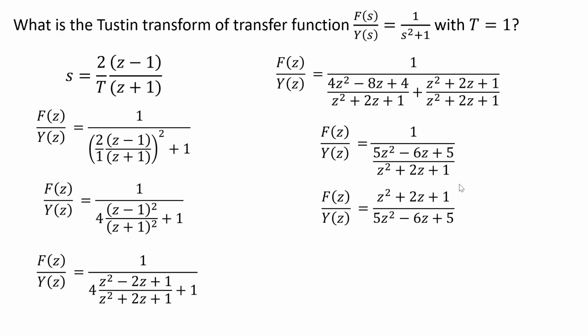because that basically means the past. Anytime you have z with a negative, that's the past sample. Z negative 1 is the last sample, z negative 2 is 2 samples ago, right? And so it basically just takes some algebra to figure that out. But once you have it in that form, then you just say that anything that's z to the negative n times a value is just that signal value that many samples ago, where you use the exponent.